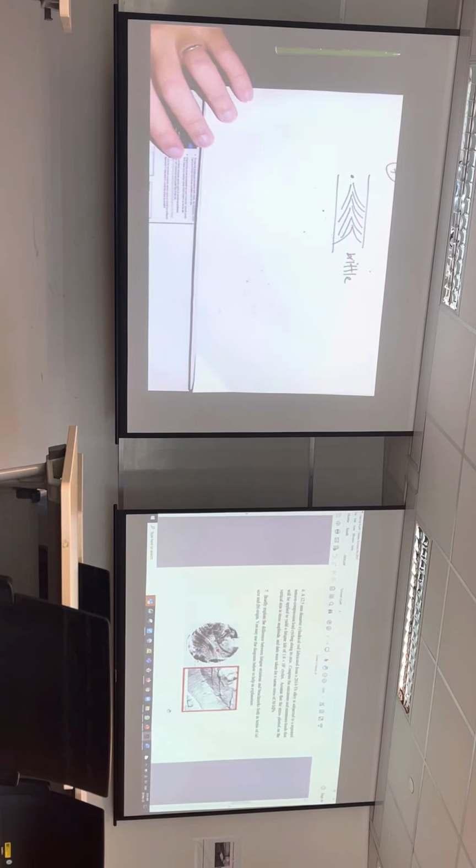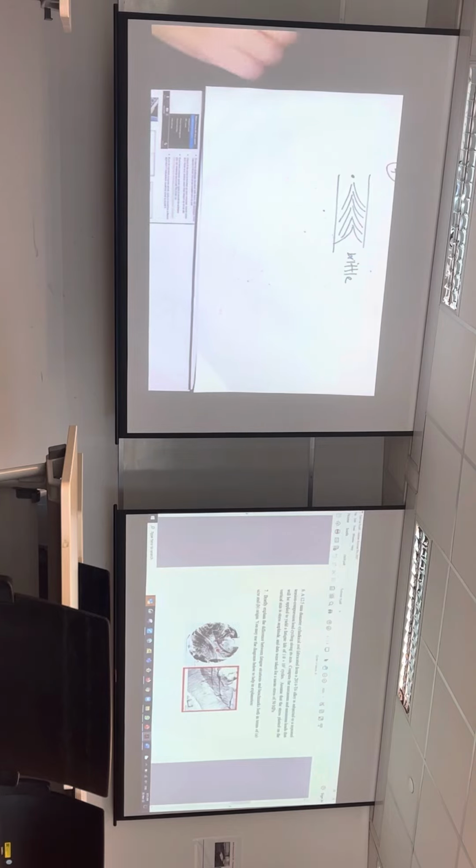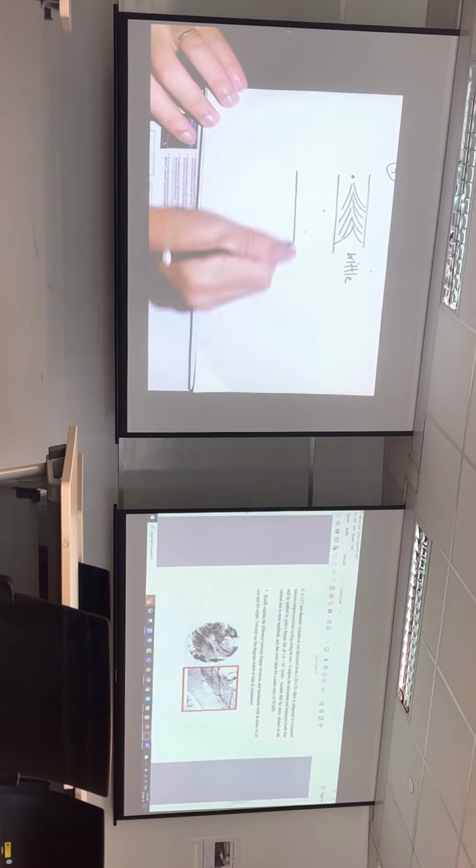In a fatigue failure, a lot of people, when they look at here, they couldn't figure out, is this a fatigue failure or is it a brittle failure, because there are lines. One simple way to remember is, for a fatigue failure, the crack usually opens slowly. Every time it opens, the crack gets bigger. So when you start to see a failure that looks like this, right?